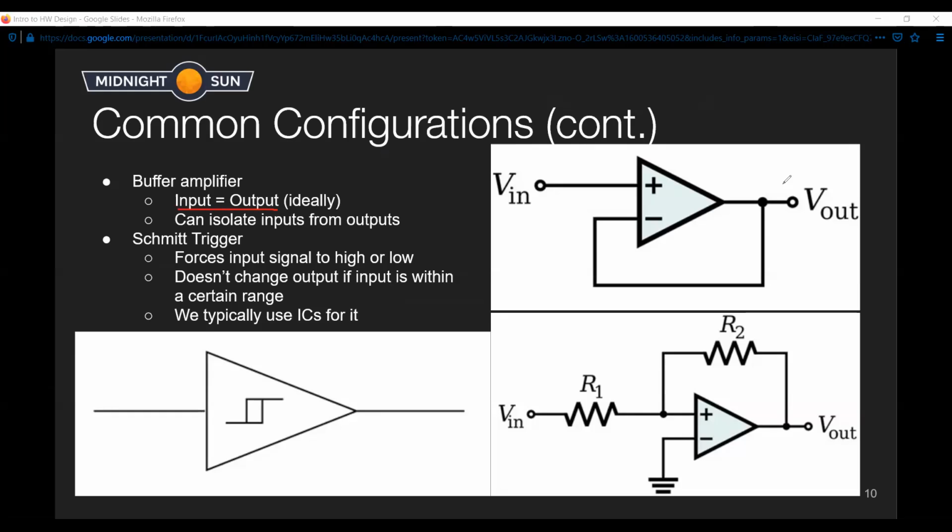And the way the op amp does that is that current going through here and through here equals 0. So you won't have the voltages on this side messing with the signals on this side. That's how it works. Is that clear, or is there something else you want me to go over?